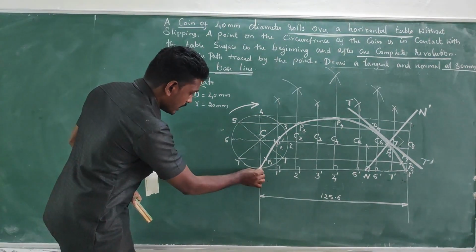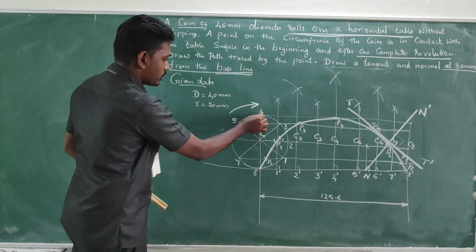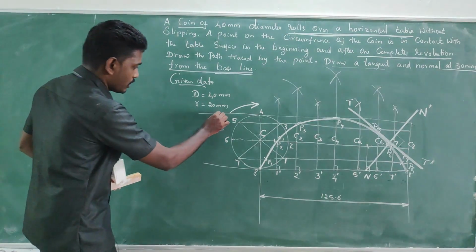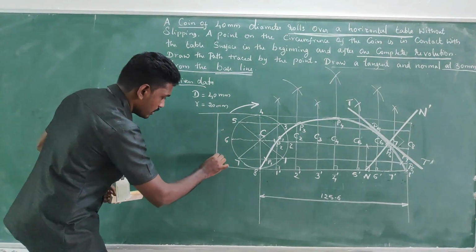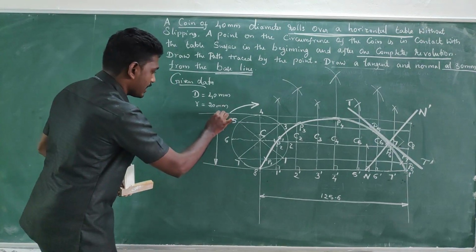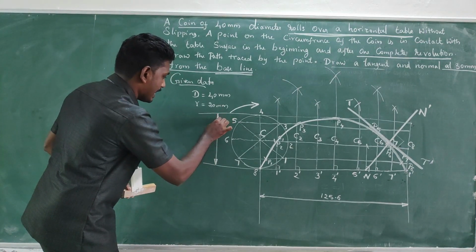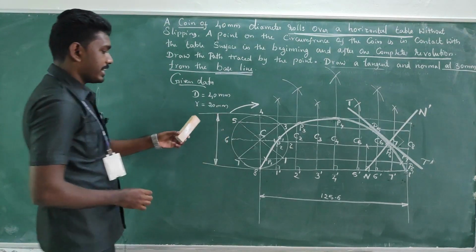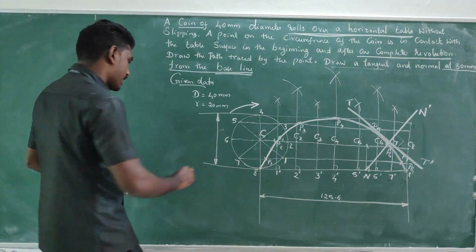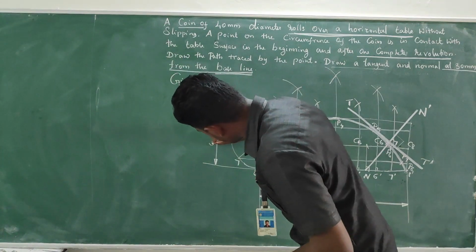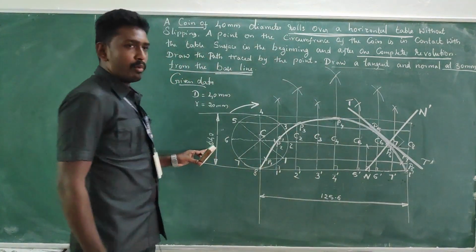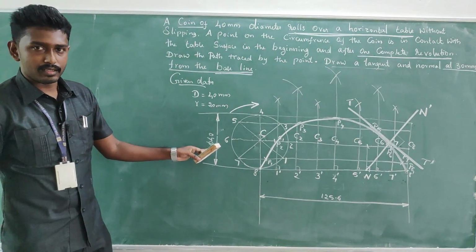From each end you can take an extension line with a thin line, and you can draw a vertical line with the ends carrying arrow marks, filled arrow marks, and write pi 40 as diameter above your dimension line, right?